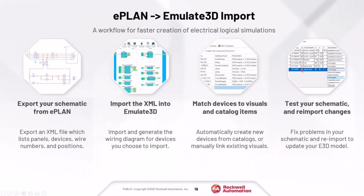You can also import all of the connections, meaning the signals. That way you have the blocks and the signal numbers, and then you have automatic linking between signals that have the same name. That's where, in the EPLAN environment, the wire numbering according to signal number is important, so that all of the connections that are connected together have the same wire number. And that's what Emulate 3D uses to tie all of the signals together.